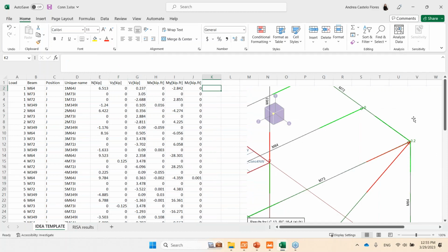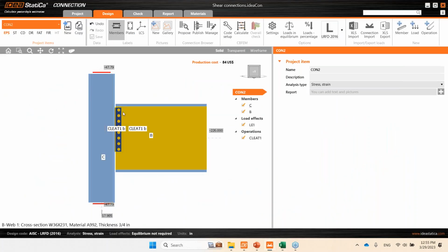Yep. Awesome. And actually going back to the question that was asked just before about the location of the shear force and whether it would be more conservative, there's a bit more precision. The user was asking whether it could be more conservative to have the shear at the node rather than in the bolts, for example, in a shear plate connection like the one you're showing here. And yes, that's very true.